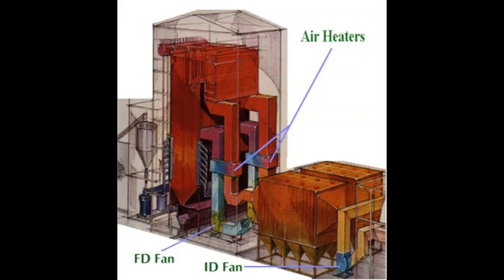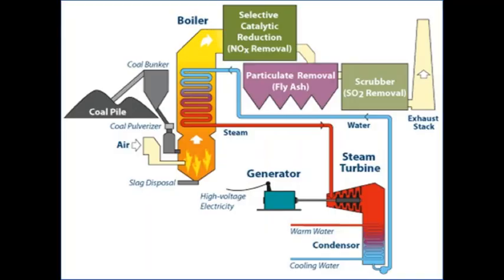If we cannot dry the coal, we cannot fly the coal. So drying is ensured, so that during pulverizing we are not getting paste, but we are getting dry dust of pulverized coal. And this hot air gives sufficient ignition temperature in the combustion chamber, that is furnace, so that quickly the fuel can participate in the combustion process.